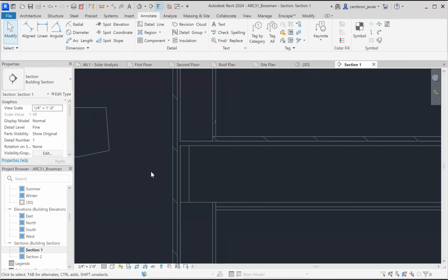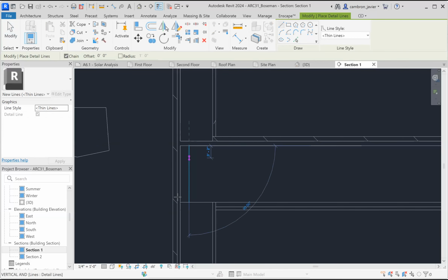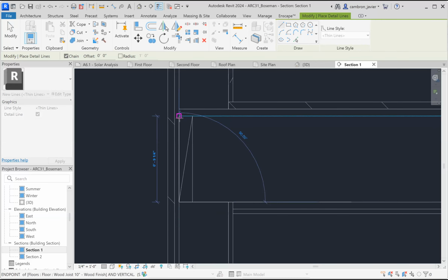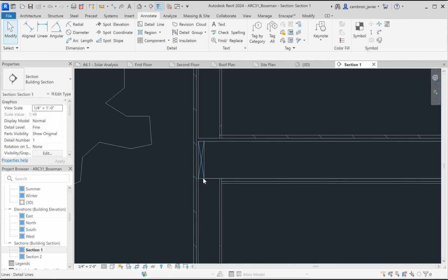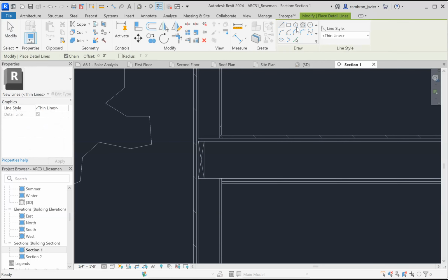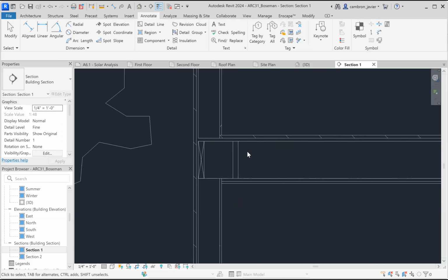So this is probably a 2 by 10. If I wanted to, I can also just draw another line to show, whenever we have any framing, we'll represent a joist with an X, representing that we're cutting it through. Now I can continue on and begin to explore some of the rectangle tools and create it that way as well. So that becomes a little bit faster.